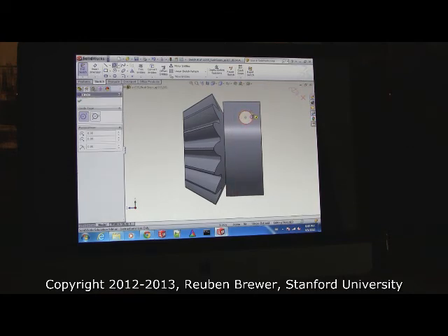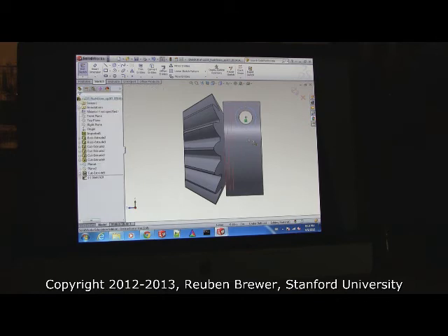Circle in the center. By the way, if it doesn't appear in the center, right here. See, it's not the center. Right here. What plane are you sketching on? The first plane, the one furthest away from the last cut we made. Basically, we're making a similar cut on the opposite side. Okay? Put the circle in the center, and now watch my screen for construction. Now we're good. Everybody good?